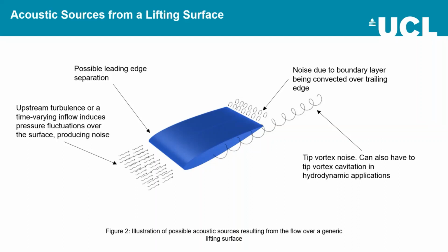Tip vortex noise is particularly important for rotating machinery, and a number of studies have shown that tip vortex noise can be the dominant noise source in marine propellers. And you can also get tip vortex cavitation in hydrodynamic applications.